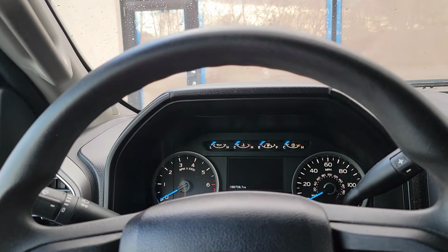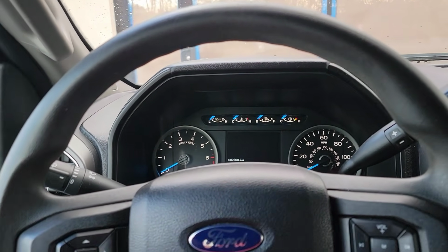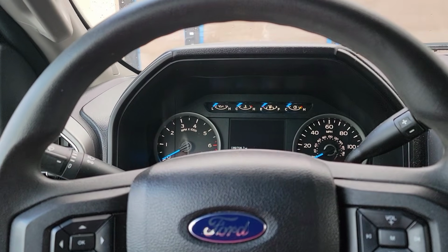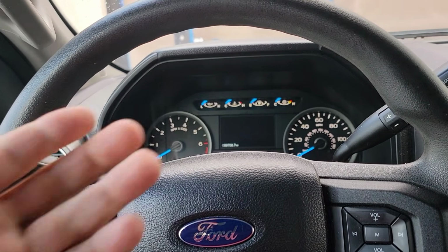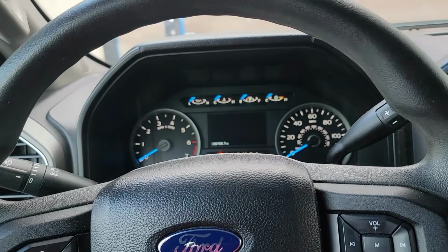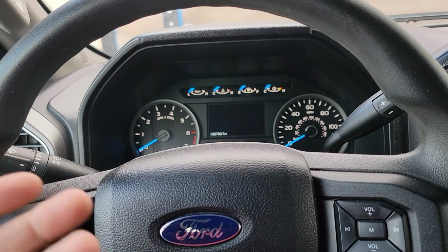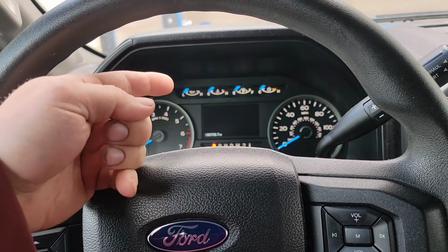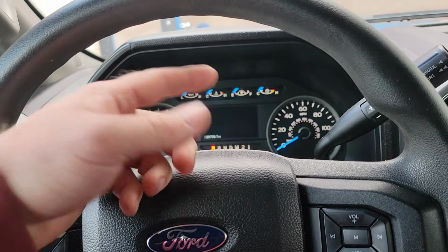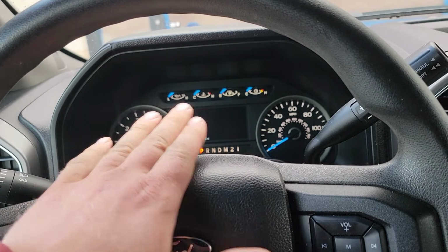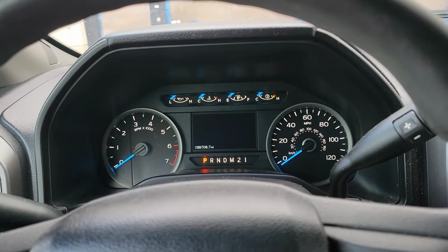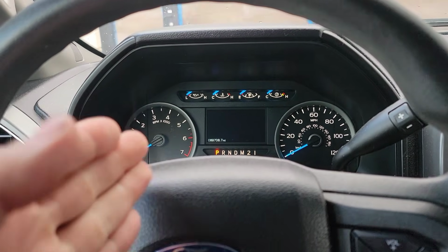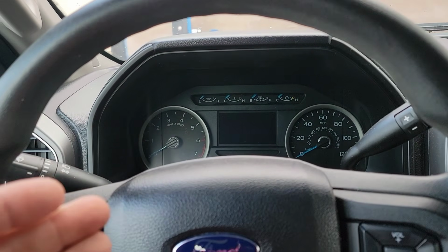I'm going to show you a cool function about your Ford. Just get right into it, and we're going to go from there. They have a mode that you can actually look and see what's going on. Some of the stuff's going to make sense to you and some of it's not. See how we have like trans temp up here, oil temp and stuff like that. But what if you really wanted to know what the trans temp was? There's a way that you can actually do that and see the exact trans temp.